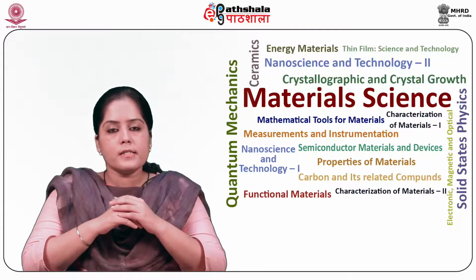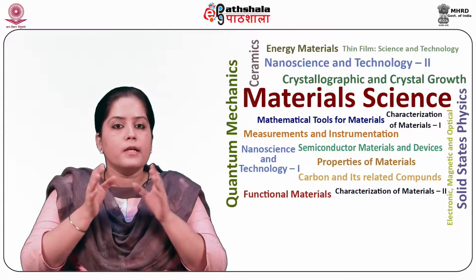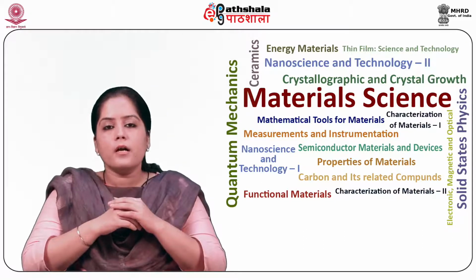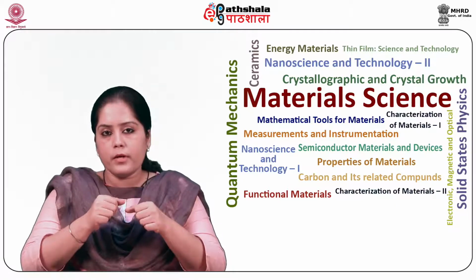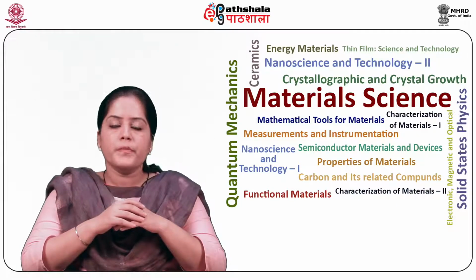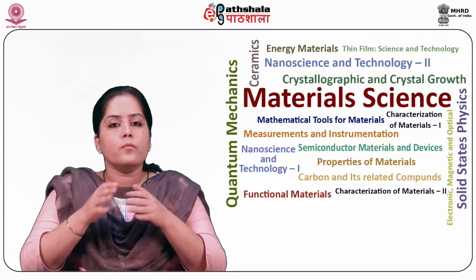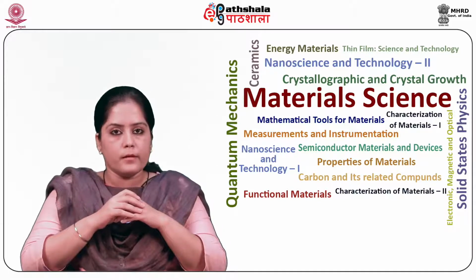High packing density, film characteristics as a function of depth. Less stress film is obtained. Disadvantages are precursors are toxic and so are the byproducts. Equipment is not economical. Capacity is limited. Contamination occurs from precursor and carrier molecules. Stoichiometry is hard to obtain.